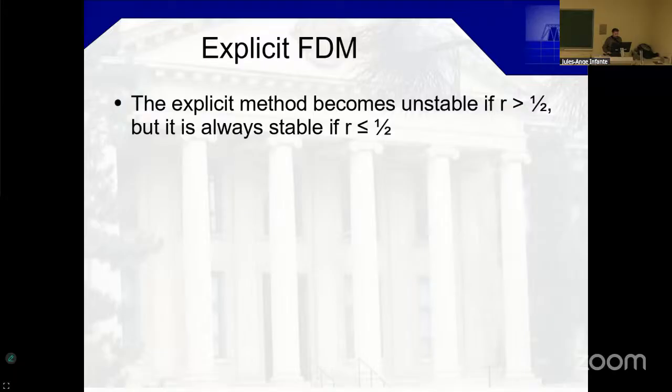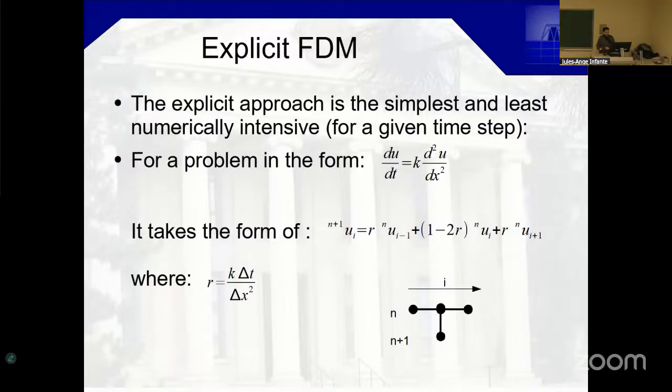Basically, we are trying to solve for our node i at the next time step. So we look at the previous time step, and in this case, we've put everything that had the same previous time step on the right side and the next time step on the left side. And we end up with the variable like this, as long as we have a uniform K, obviously.